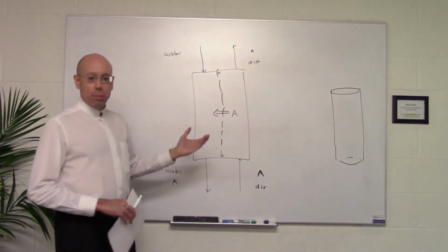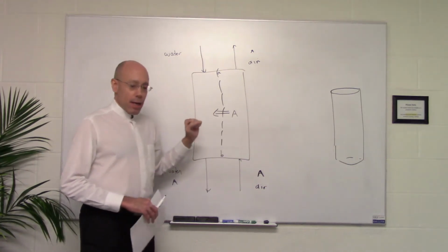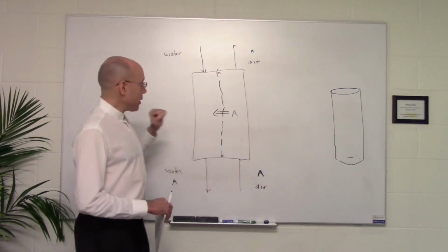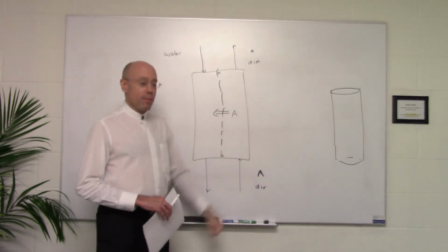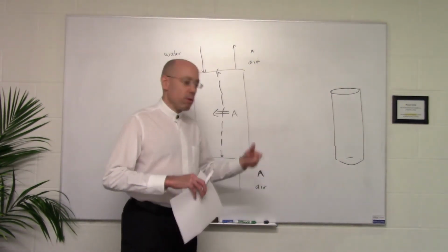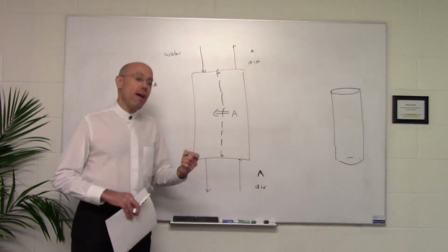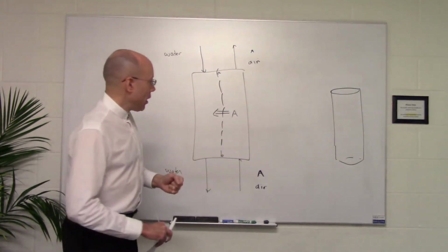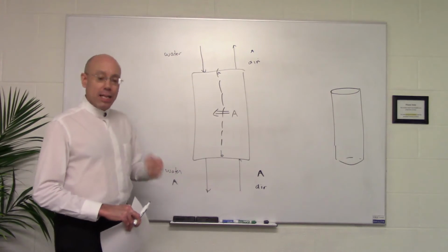Because if you give an ammonia molecule, say, a choice of being in the gas or water, air or water, it has a certain preference for air, and it has a certain preference for water. And if the water that comes into this tower is completely clean, some of the ammonia would like to be there. Now, an individual molecule is not a sentient entity with power of choice. When you say a molecule wants to be there, what you really mean is that it's energetically favorable for it to be there. And if you just have a system and let it relax to equilibrium, be the way it wants to be from energetic considerations, some of the ammonia will actually want to sit in the water.